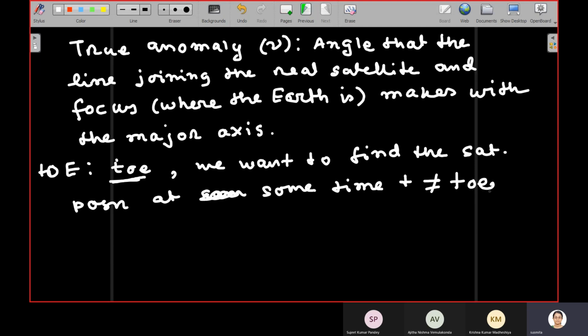If the perturbation parameters are not broadcast by the satellites, then we have to take the same semi-major axis and eccentricity. Longitude of ascending node will change over time, that is at a particular time. So depending on Earth rotation, we can calculate the longitude of ascending node. Okay, argument of perigee. If no perturbation information is provided by the satellite, we will take the same argument of perigee over the 2 hours.